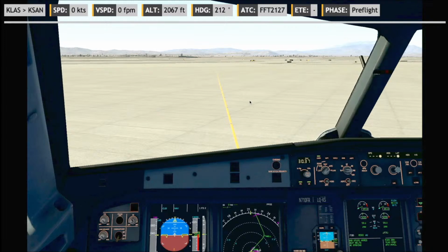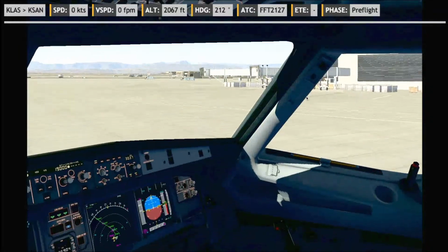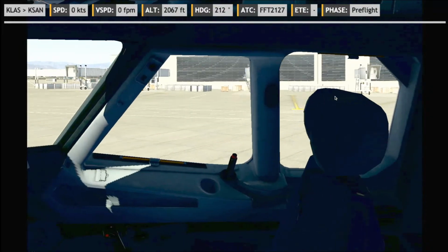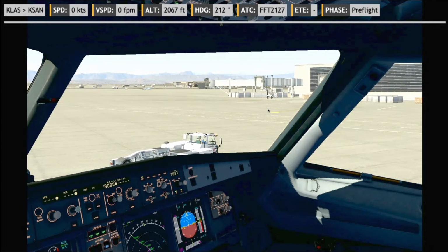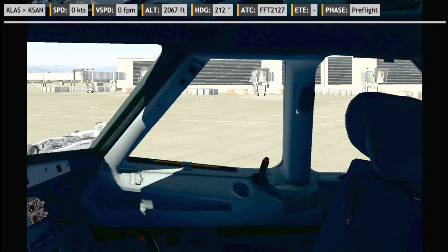Alright, thank you very much for pushing, and see you on the right side and talk to you later. So what they mean by see you on the right side is they will drive up to the right, show their red flagged pin, and then we know that our nose wheel bypass pin has been removed.